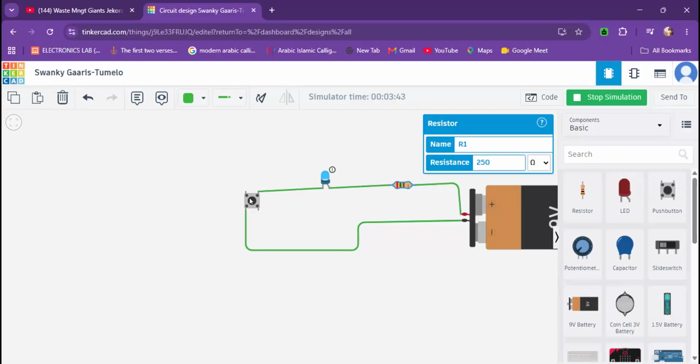Still caution. That means that you should be cautious. This LED will not last, it will burn. So let's still increase. So let's go to 300 ohm. 300 ohm, and let's test and see. You see, this is optimal. You see, so the LED will not be heating up with 350 ohm.